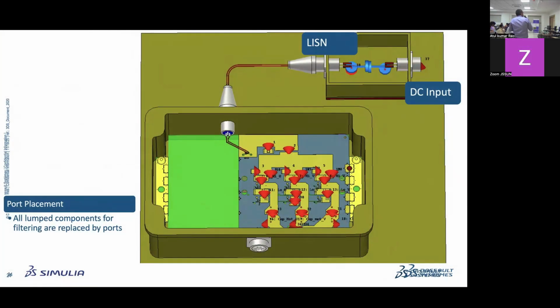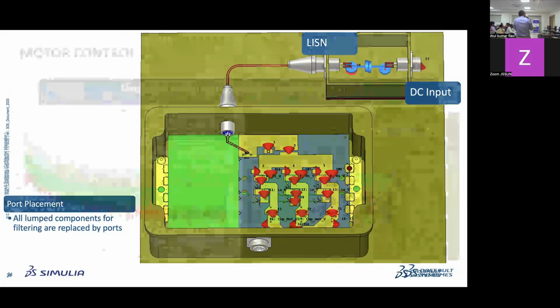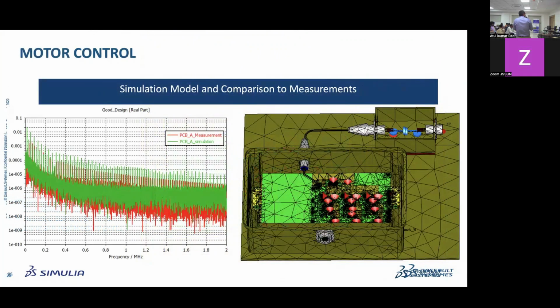Now, the same model you can build within CST itself. You have your entire structure and your PCB files created, and the red ones are the ports. Then you run the same methodology we talked about: you run a tetrahedral mesh, get the results of these parameters, go to the circuit schematic, connect all the components, and run the simulation.